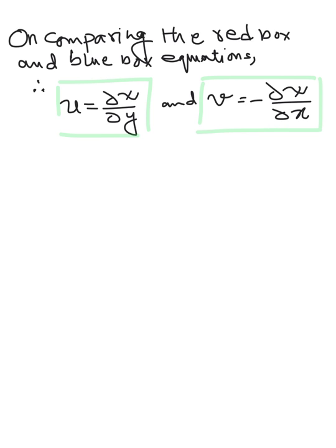The good thing here is that a scalar function psi can exist for a typical flow field. There are some conditions that have to be satisfied, and once I have that stream function, I can easily determine the corresponding velocity distribution for that particular flow field. Now, these two equations automatically satisfy the continuity condition. So it means that a stream function automatically satisfies the continuity condition.